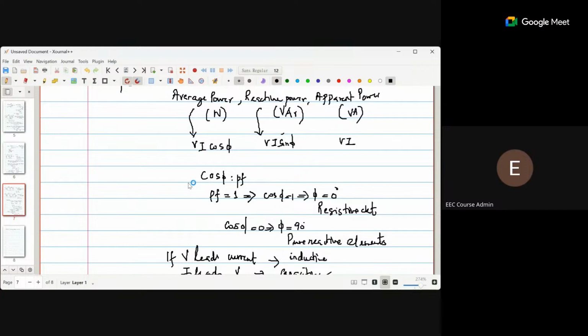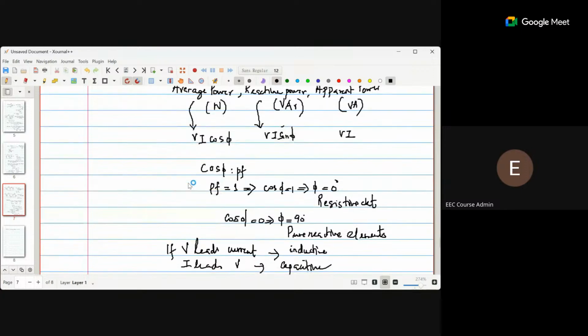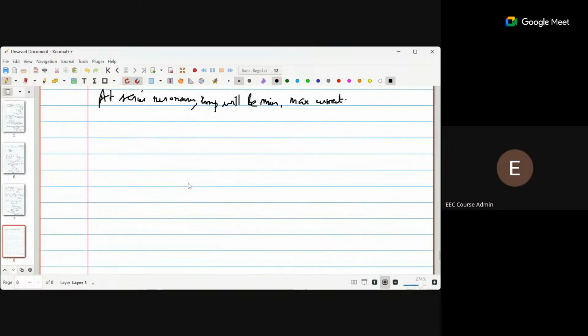The main point that you need to take care of: if it is in the time domain, you know that say V of t is Vm sin omega t, this Vm is the peak value. Other than that, if it is simply given in polar form, say 10 angle 0, without specifying anything, then by default you consider this as the RMS value.